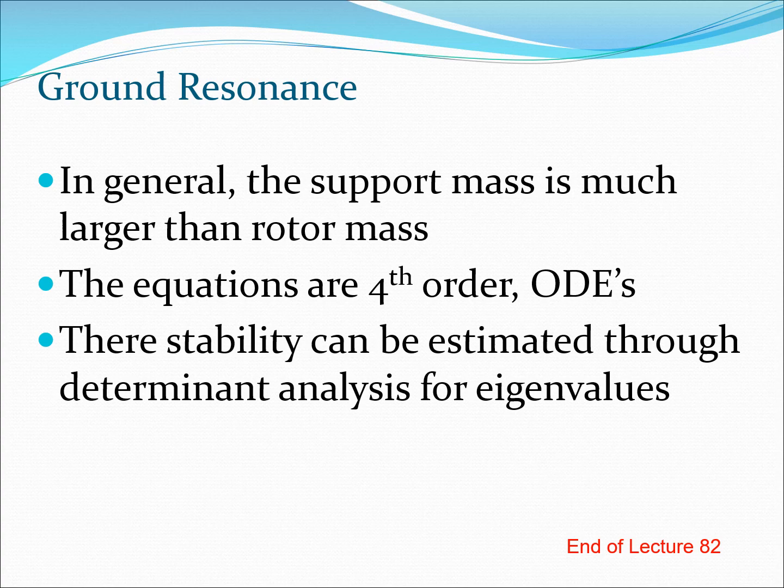So again, this is a clear case where FCT is required, because we need to transform the equations of the lag motion from the rotating system to the fixed system. And once we do that, the simplest model we can have is the 4DOF model, and with that we can predict some of the ground resonance phenomena. Now, of course, if you wanted, you can have more degrees of freedom also, and there are of course models where more degrees of freedom are used, but this is the simplest model you can have, through which you can capture the physics of the problem. And again, through the principle of scientific parsimony, we always want to keep the simplest model which we can do with in any physical situation or in any engineering situation.